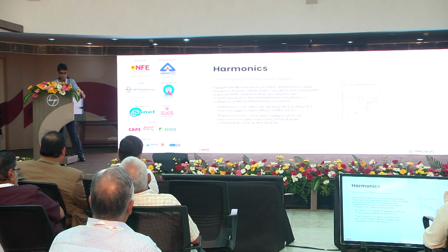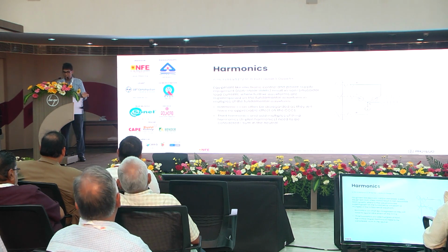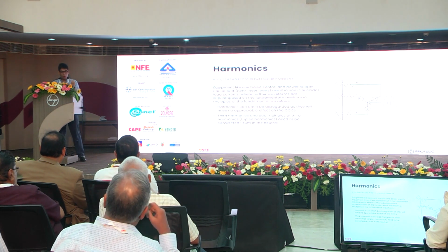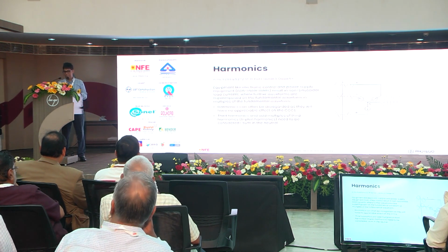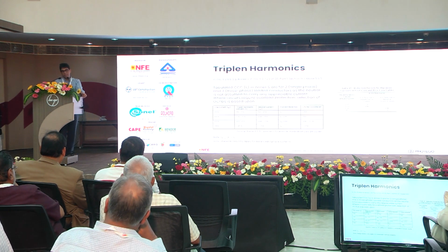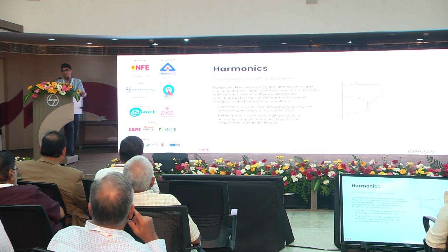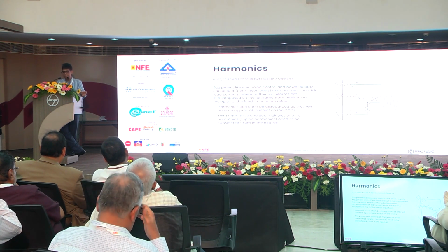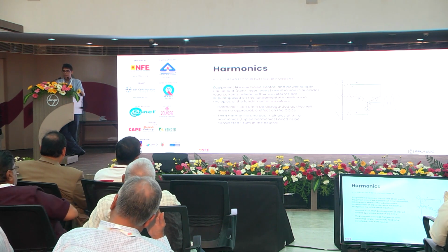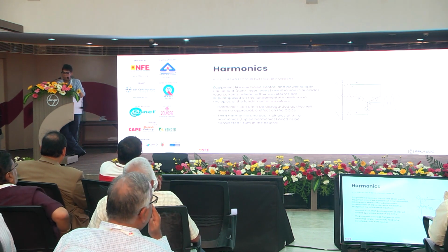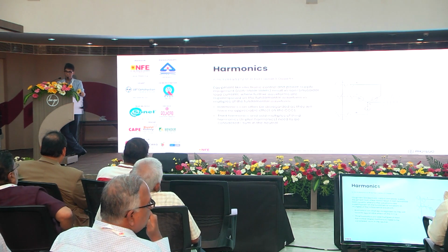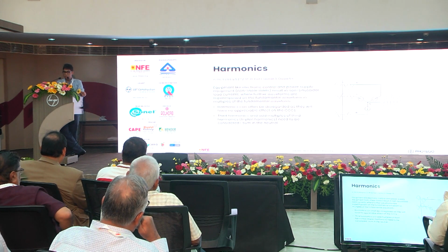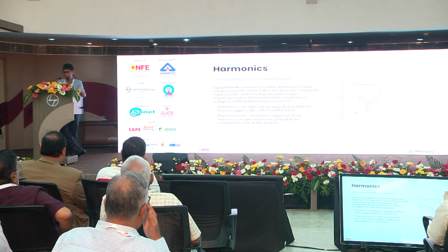Now harmonics. Very often we are told that harmonics have an effect. The truth is that the significant ones are the third and odd multiples of the third harmonic, because these sum in the neutral. Let me just go into this a little more. When you have non-linear loads, basically electronic control and power supply units, their waveforms are not sinusoidal. And what happens is you have a further waveform that is superimposed, which is in multiples of the fundamental frequency. The fundamental frequency we all know is 50 Hertz. So this may be in multiples. So this say is happening.